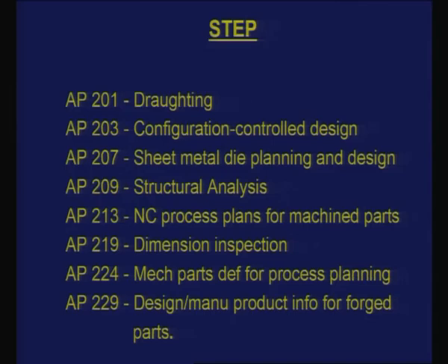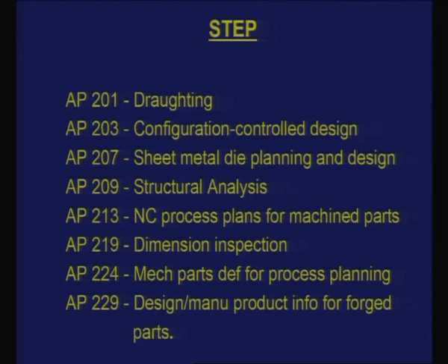For example, if I have AP209, I can exchange finite element analysis information. I have done finite element analysis, let's say in one package, and I would like to see the results in another FEM package. Though the analysis is done in this, it should be possible because both of them give you an option to translate the data with AP209. So you are going beyond geometry when it comes to these applications. STEP is still under development, but many of them are already international standards. So this offers one of the options for exchange of product data.